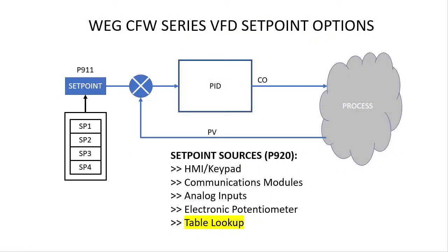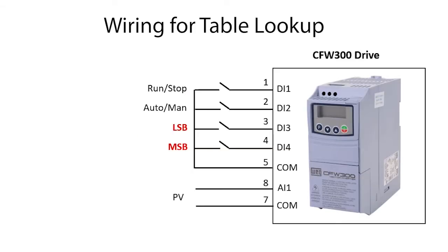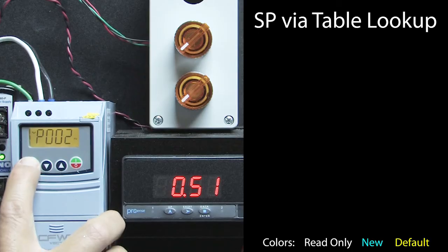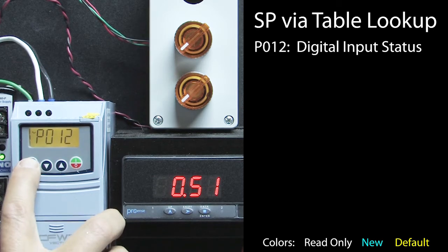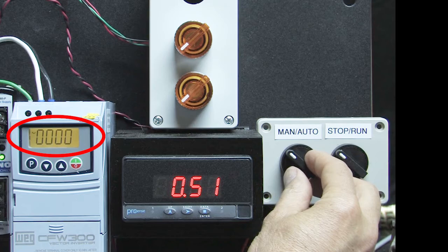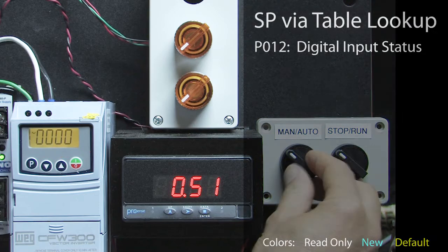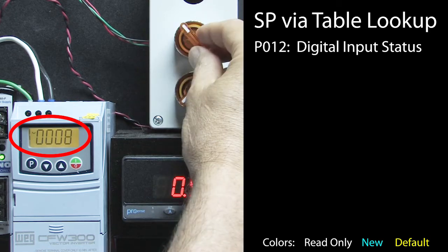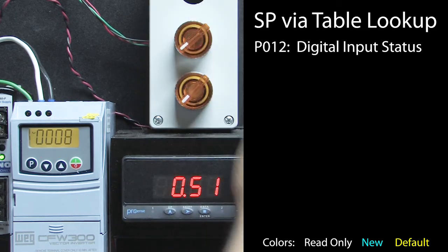Finally, you can have up to 4 predefined set points, which you select using digital inputs 3 and 4. The wiring is exactly the same as the electronic potentiometer we just did, but this time I'll use discrete switches to enable each bit. Let's go back to parameter 12 to view the digital input status again. This time, I'll disable the auto manual switch so it's easier to read the results. Sure enough, this switch controls digital input 3, and this switch controls digital input 4. Perfect. Looks like I wired it correctly.